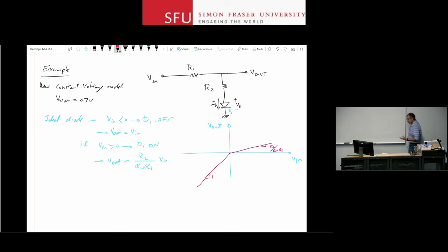And when you're drawing these characteristic curves for your assignments or quizzes later on, that is the information that we need to see on that curve. We want to know where the breakpoint is, where the slope of that curve has changed, so it changes at 0, 0, right? And what are the slopes of those pieces of line before and after each one of those breakpoints? Now, something that should help you in analyzing these circuits is that the number of breakpoints in the characteristic curve is at most equal to the number of diodes.